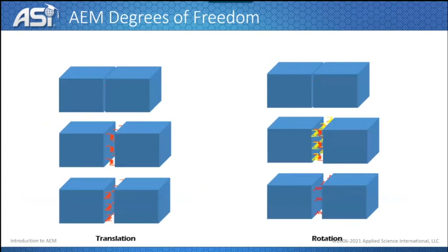So in the finite element method, if you are using a brick element or a solid element with 8 nodes, you have 3 degrees of freedom at each node if you are solving using FEM, leading to 24 degrees of freedom for each element.